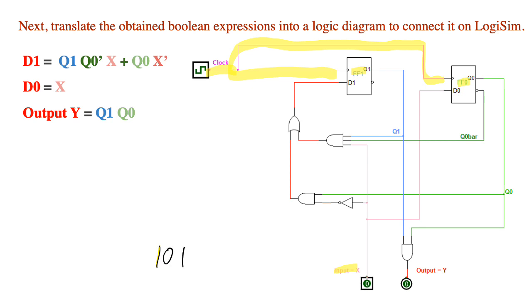What you'll do is, when the clock is 0, input the first bit in the sequence and then wait until the clock rises from low to high, so it will read in your input X, and only do your changes when the clock is off or 0, so that when the clock transitions from low to high, it will actually read in your input.